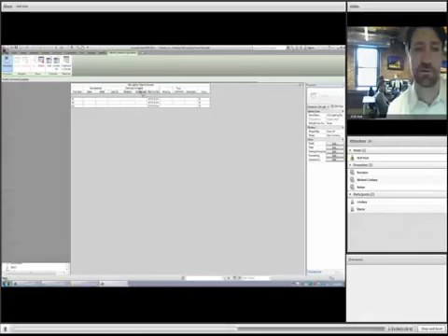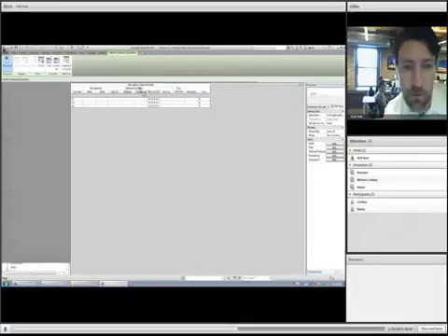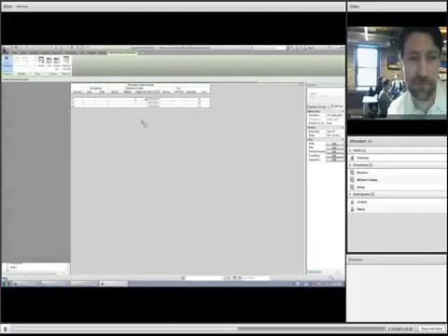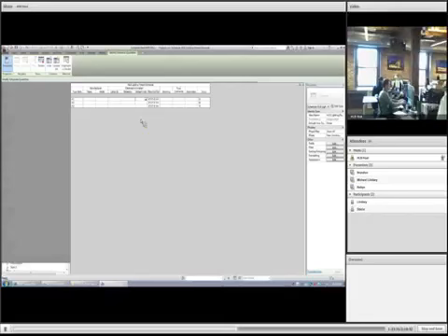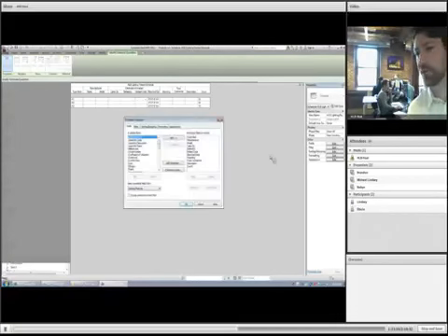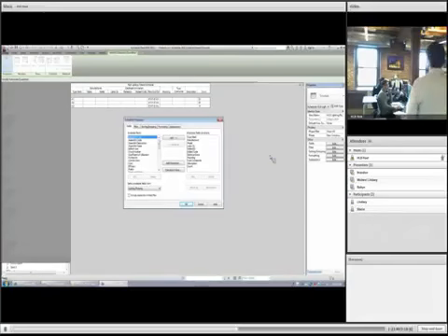Electrical information. There are other things that you can do in there. We could sort by level. What if you wanted to have your lighting fixture schedule determined by level? And you would maybe want a summation for each level of the number of fixtures that you have.